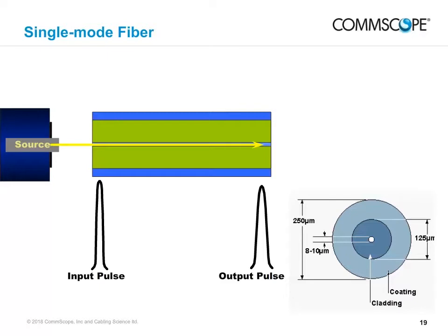Single mode is used for higher data rate and longer distance requirements and is commonly used for long-distance telecommunications links. Standard single-mode fiber is optimized for performance with light of 1310 nanometer wavelength, which gives minimum dispersion. Non-zero dispersion fiber is optimized for performance between 1530 and 1565 nanometers. Some long-haul systems use this single-mode fiber at 1550 nanometers.